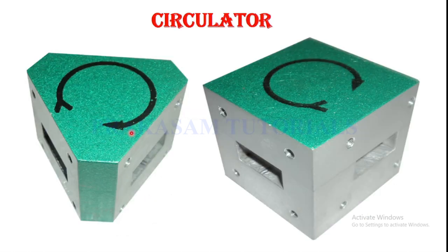And the next waveguide component is the circulator. So this is the circulator waveguide component. And what is a circulator? The circulator is a multi-port junction device in which a wave can flow only from the nth port to the n plus 1th port in one direction. This is a 3-port circulator in clockwise direction: port 1, port 2, port 3. There are two types of circulators and their S matrices, that is, the clockwise circulator and the counterclockwise circulator.